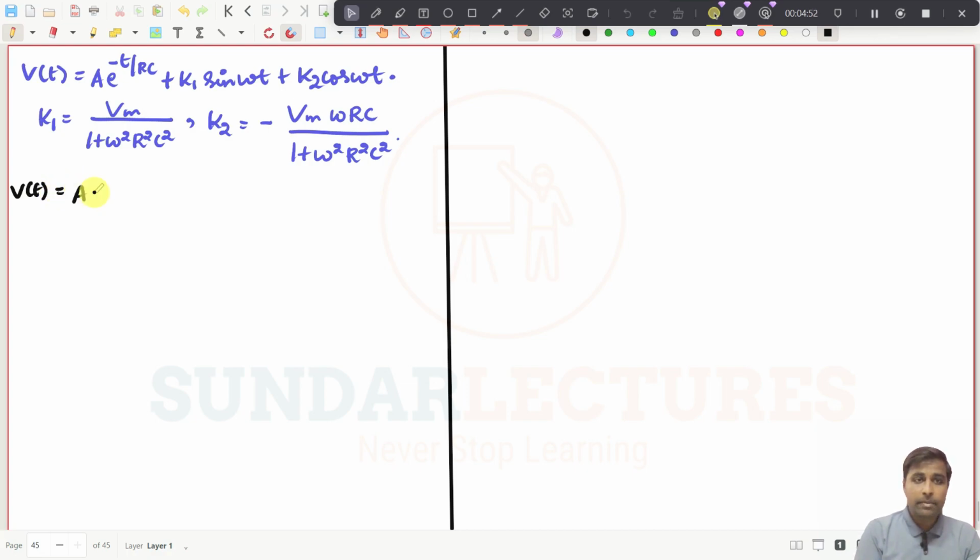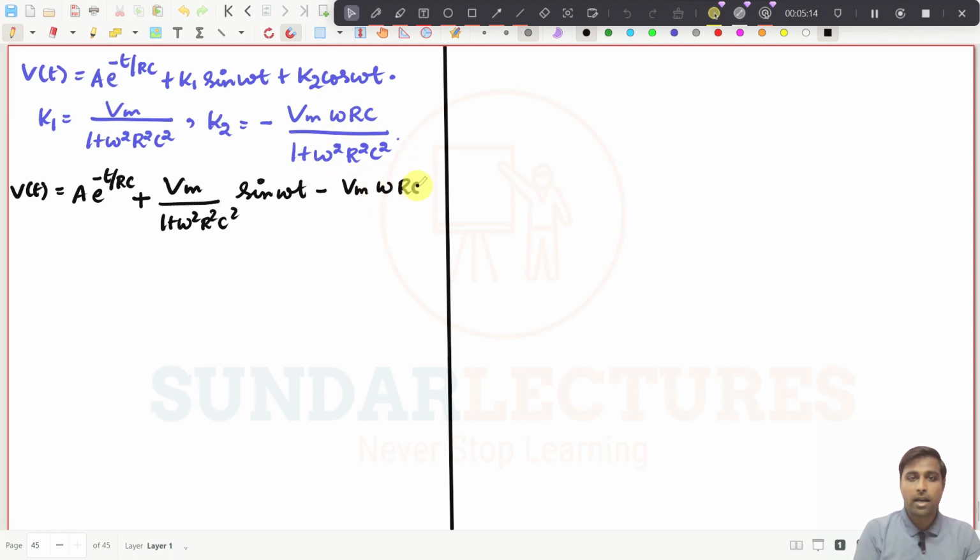So V of t can be written as A e power minus t by RC, then this is K1, so it will be Vm divided by 1 plus omega square R square C square into sine of omega t, and then minus this K2, whole K2 will come, Vm omega RC divided by 1 plus omega square R square C square into cos omega t, right? This is the value now.